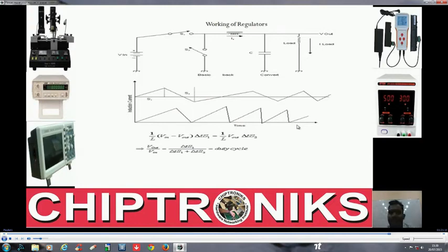Like in the case of a notebook motherboard, at the higher point, that is at the DC jack, we have the adapter voltage, whereas at the ending point, that is at the CPU, we have the least voltages. And how does this voltage conversion take place? It is the work of the various regulators present on a notebook motherboard to convert the adapter voltage into the lesser voltages required by components like the south bridge, north bridge and the CPU, right?